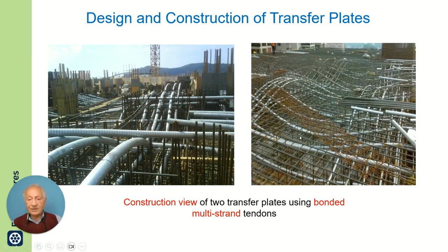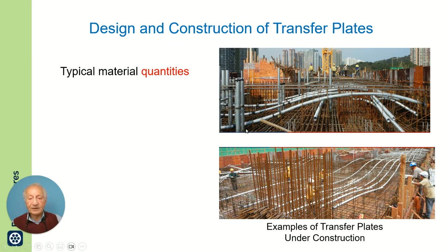The two images are views of transfer plate reinforcement. What you see is the ducts of grouted post-tensioned members going up and down, configured to raise the load here at midspan and deliver it to where the supports are. Another example of the transfer plate.